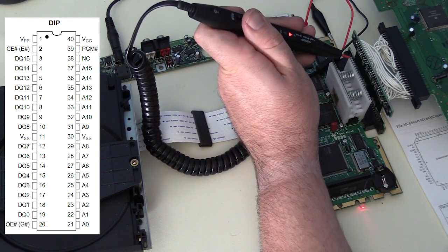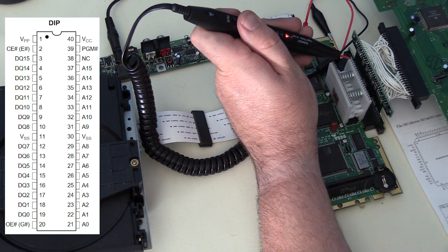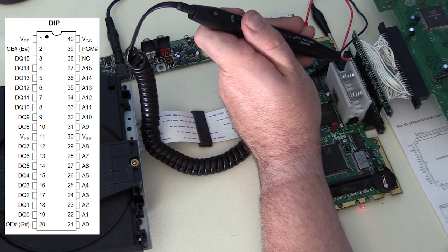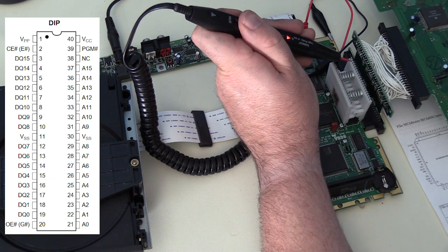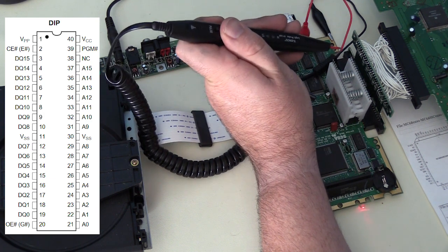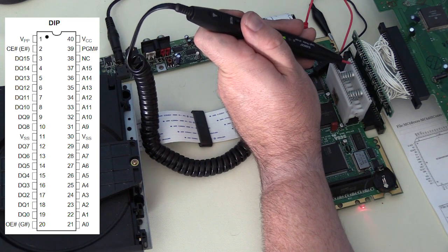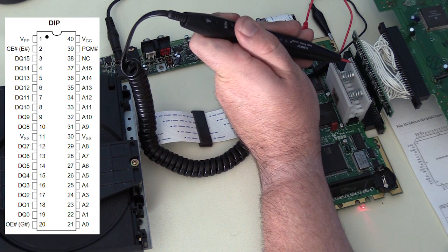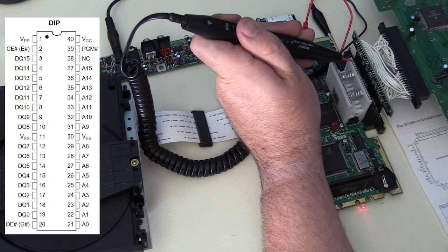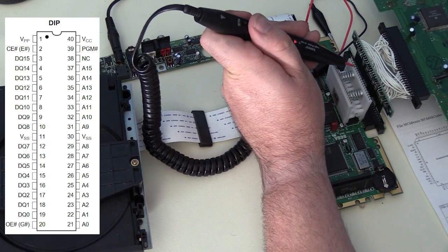So we've got voltage is holding high. This is a programming pin that the EPROM programmer would use. It's just going to hold high on a Genesis. And let's see, that one shows is not connected in the diagram, but it's reading low. That's okay. And then the rest of these are going to be address lines, so they're going to show flickering